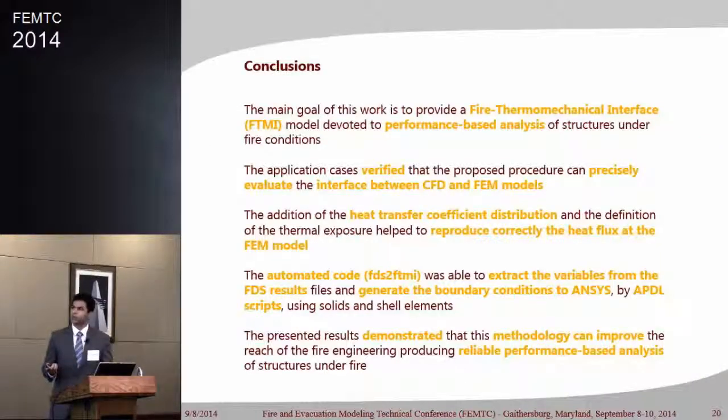So to point out some conclusions, the main goal of this work was to provide a fire-thermo-mechanical interface model for performance-based analysis of structures under fire. The application cases verified that the proposed procedure can precisely evaluate this interface between CFD and FEM models. And the addition of the heat transfer coefficient distribution and the definition of this thermal exposure help to reproduce correctly the heat flux at the FEM model.